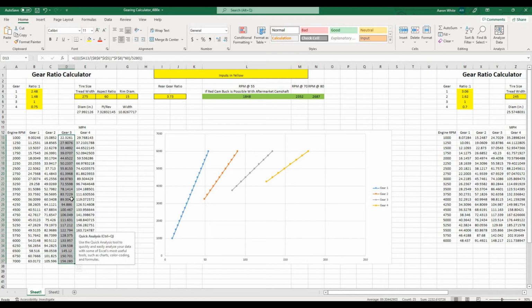So the way you need to think about this is, where am I going to be at 2,000-ish RPM, where I want it to lock up at very low throttle? What amount of throttle with my converter do I honestly think will be 2 to 2,500 RPM? 2 to 2,500 is going to be in the 45 to 55 mile per hour range.